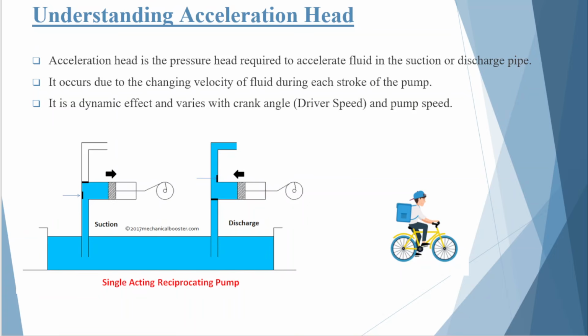Now we arrive at the most important concept of this presentation. So, what exactly is acceleration head? Acceleration head is the additional pressure head required to accelerate the liquid inside the suction or discharge pipe during the piston motion. To understand this better, imagine a long suction pipe completely filled with water.